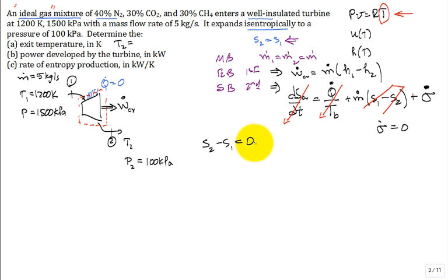And I know that I can get an analytic expression for the change in S of an ideal gas mixture. It is C sub P, natural log of T2 over T1 minus R, natural log P2 over P1. Do you agree? Yes. Does that equation look good? Yes. But how do I get this C sub P and R?